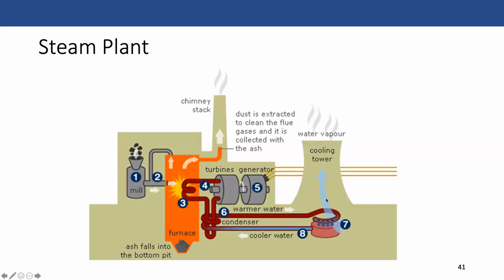And so all of the stuff coming out of the cooling tower might be coming from a river nearby. And so you can use that water, even though it's really impure, to cool down the closed cycle water loop. And then you send that back out, and some of it is going back into the stream as warmer water, and then a lot of it is going through this cooling tower and evaporating as water vapor. So these things can actually have a pretty significant amount of water use as well.